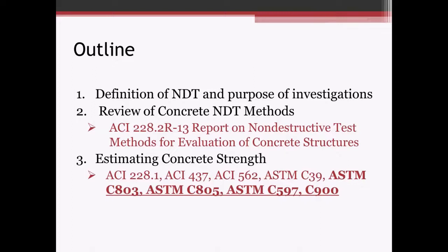There are different methods, downhole seismic methods, where you can drill a hole adjacent to the foundation and drop a geophone down the hole and see how it reflects off of the adjacent structure. So if you know there's a footing 4 feet down, you're getting a reflection 4 feet down.